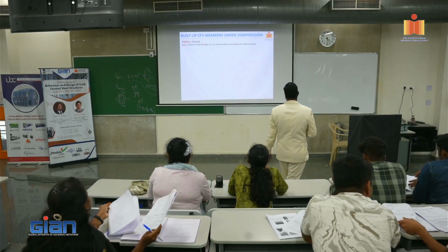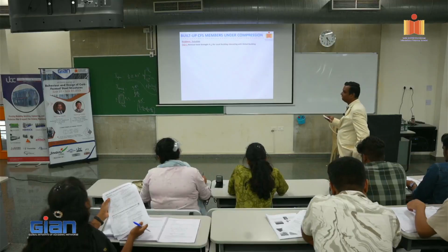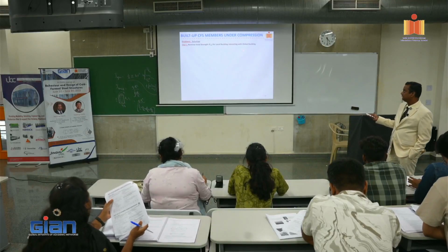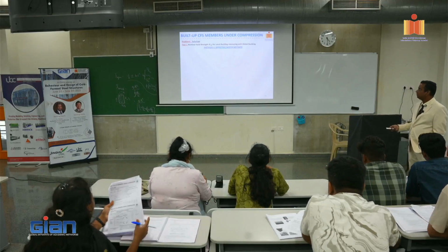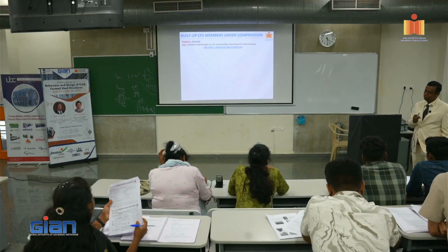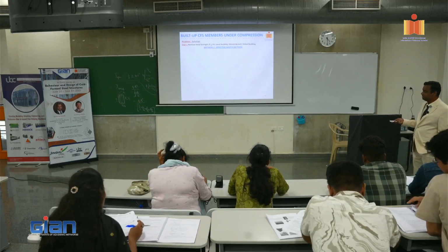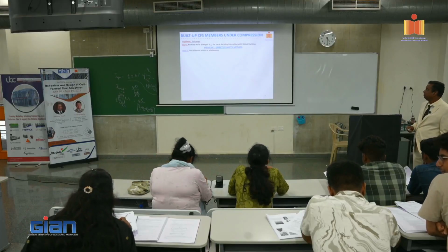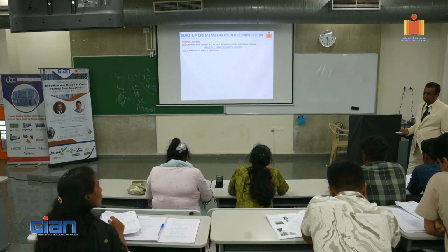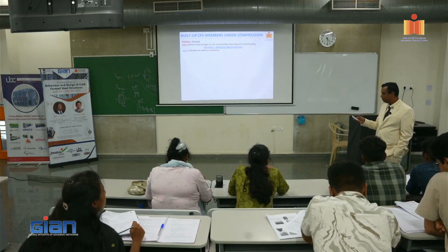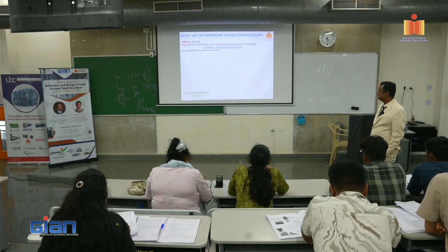Right? Now, nominal axial strength for local buckling interacting with global buckling. So, method 1, as I told you, two categories. First category is the effective width method. So, find the effective width of all the elements. That is very simple. You have to take piece by piece. What are the several pieces here?